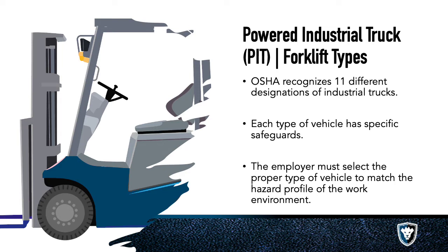And a lot of the different classifications for forklifts, just to keep this basic and quick, has to do with the atmosphere or the environment you're working in. So if you're working in an explosive atmosphere where you have LEL floating around or dust floating around that could ignite, you don't want to use something with a high heat output like a diesel forklift, right? You're probably going to want to use an electric forklift that has some of the Class 1, Div 1 or Div 2 encasements for the battery and the engine and all those different parts. So that's really what it comes down to.